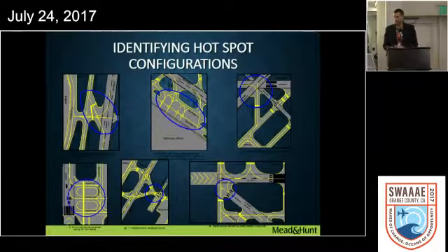So some examples of the hotspot configurations that they're noting. The first one is where you have the high-speed exit, so you have multiple taxi lanes, large, vast, open pieces of pavement. And the second one, they're trying to promote the addition of islands there again, so you don't have the large, expansive pieces of pavement. The third graphic is illustrating where one taxiway crosses 2 runways. The goal is to make it very clear that the pilot knows what runway environment he's entering without the confusion of going on the wrong one.